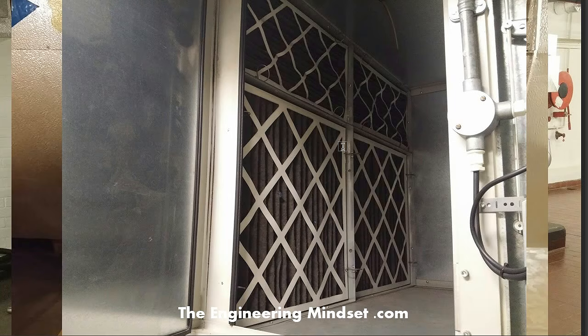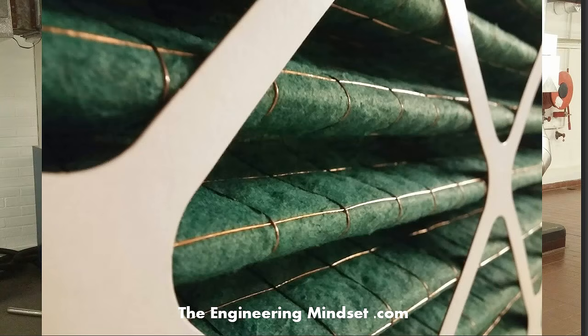But these filters will become blocked over time as more and more air passes through there. These filters will pick up all that dirt, and it will get to a point where the pressure drop across the filter becomes huge, because the fan is trying to pull all this air through, and it's blocked by this. Let me just give you an example. So this is what a clean filter looks like. You can see the metal frame there, and the filter material wrapped around it.